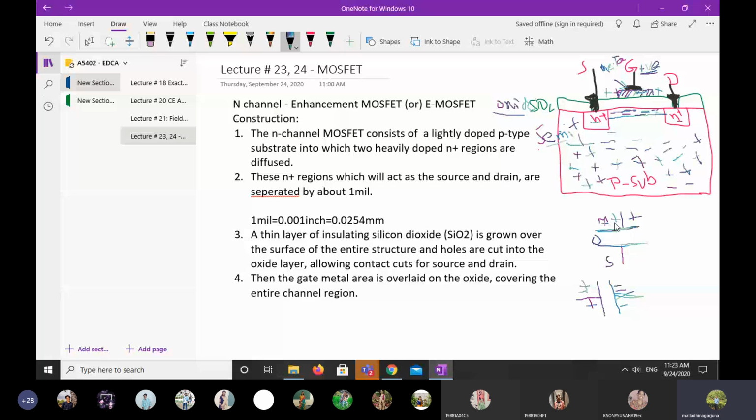Even if you apply the negative, what happens is it gives positive. So if the positive comes and is placed here, the electrons flowing from source to drain will participate in the covalent bond and will not generate any kind of electricity. For that reason, we should attract electrons only in between the source and drain. To attract the electrons, we have to apply the positive terminal of the battery. So you are applying the positive, but you are getting the negative, so it is an inversion layer. It's clear?